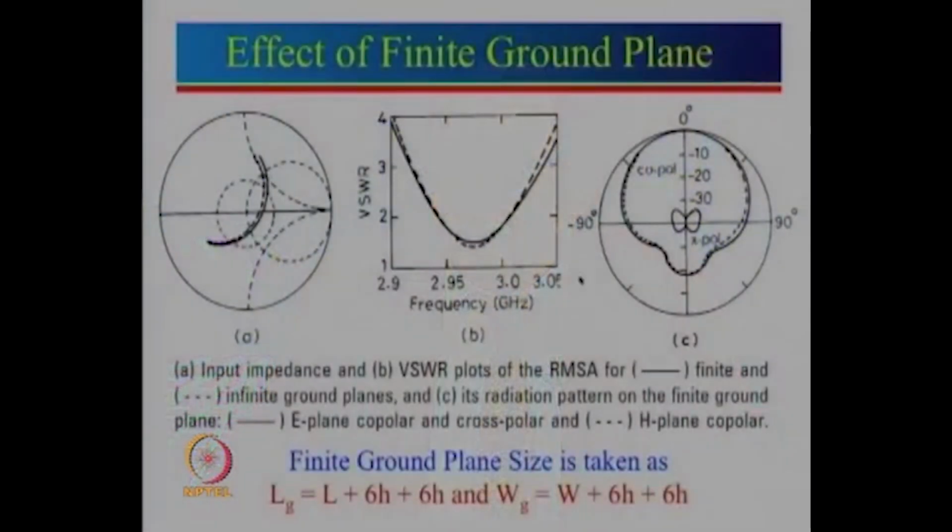So, when we were studying these effects, we looked at what is happening to the ground plane, and the moment we started reducing the ground plane size, we could see that just a single patch is radiating equally. So, that means if you take L equal to Lg, you can design a very simple bidirectional antenna. Remember, there is a disadvantage: now it is radiating in the front as well as in the back, so the overall gain reduces. But that is the property of the bidirectional antenna.